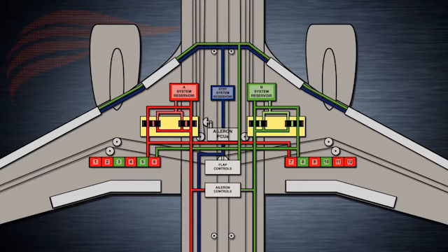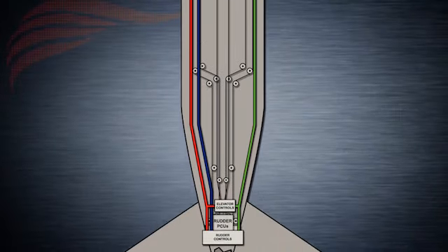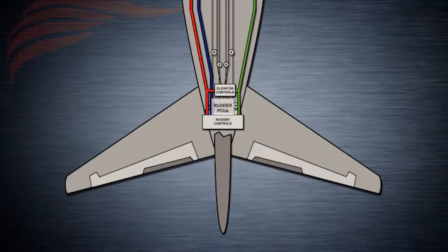Similarly to the rest of the flight control surfaces we've covered, rudder pedal movement inputs are linked to control valves in the rudder power control unit, PCU, via cables and linkages that also pass through the rudder feel and centering unit. In the case of rudder control, the pilot inputs are also linked to a standby rudder PCU that provides backup and system redundancy in the event of main rudder PCU malfunctions.